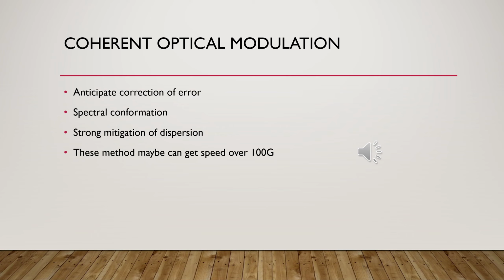Actually, in the current optical modulation, one of the advantages is that we can use forward error correction. This basically gives you a big gain in soft decision. This allows the signal to pass through a very long distance and requires fewer points to regenerate that information. This gives more margin to allow the signal bits to go a longer distance.